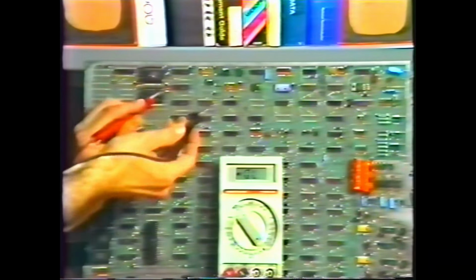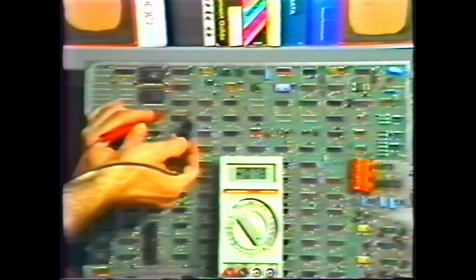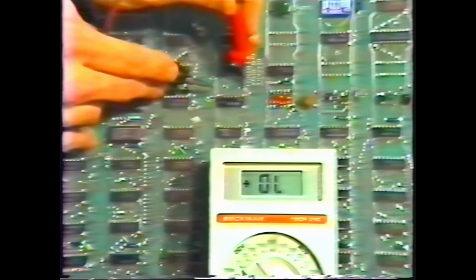And finally, let's take a look at one more test. If the printed circuit board is shorted, you can't find the short circuit with your meter set to resistance. Look, no matter where we test the board, when we measure resistance across the power rails, the board appears shorted. It appears shorted everywhere because all the rails are tied together. The short will often be caused by one of these small capacitors which are wired directly across the power rails. They look like diodes, but they're capacitors.